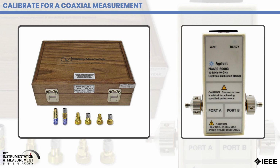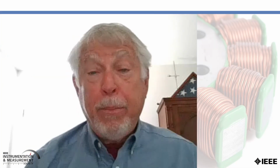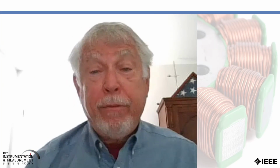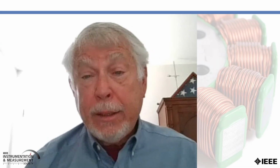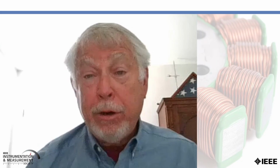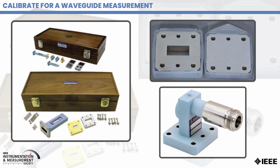Here you make the connection to the end of the cables once, and the network analyzer will switch the eCal system to known states. Waveguide calibrations can be done using an eCal, but because of the simplicity of the calibration standards, it's much easier just to go ahead and do a TRL cal. In this case, we'll use a through, a short applied to both ports, and a quarter wavelength section of the waveguide.